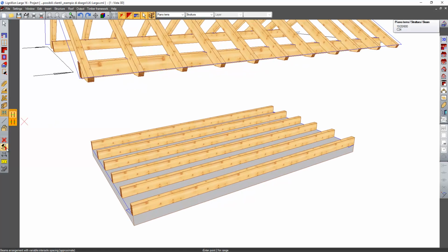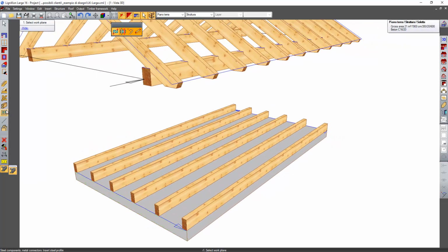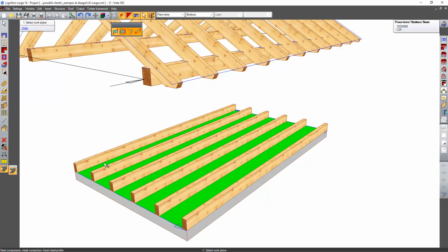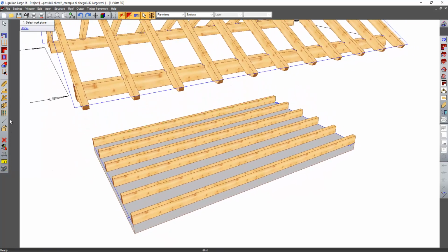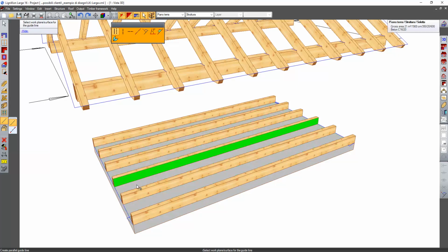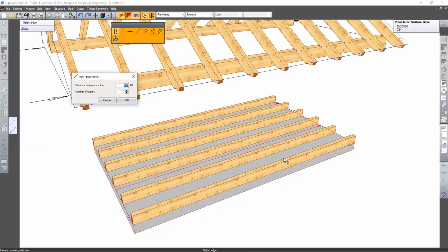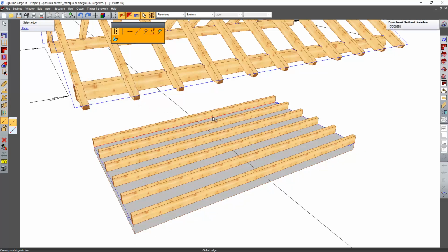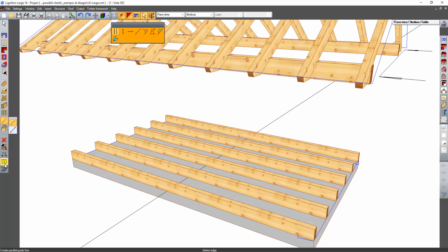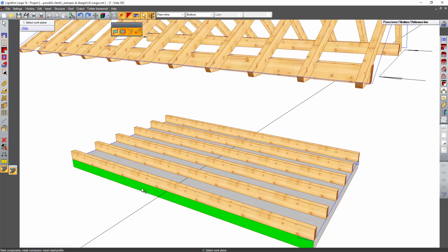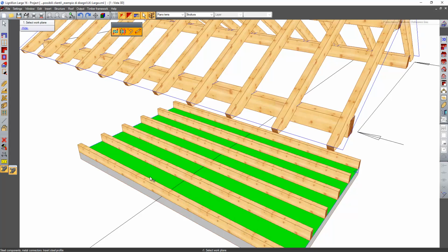Now we would like to put a steel element. We can do it also with a single beam like wood, but also a steel element, and we are going to put it in the middle. So first the best is to add a guideline here to have a reference. So this is 600. Okay, we can divide by 2, it will be 300, of course. Confirm it, and now from this point we click the steel element, the beam, and we go to select where to draw.